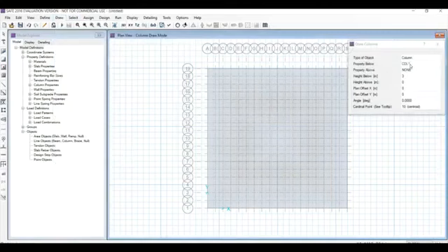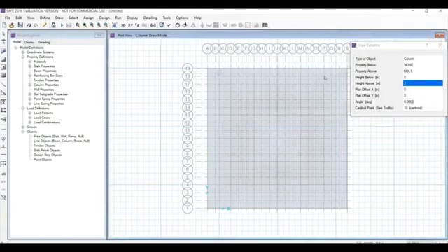Column 1. Make sure that below is none. Above is column 1. Height below is 0. Above is, let us assume, 2 meters of plinth beam level. Then go for 2, and then draw the column.